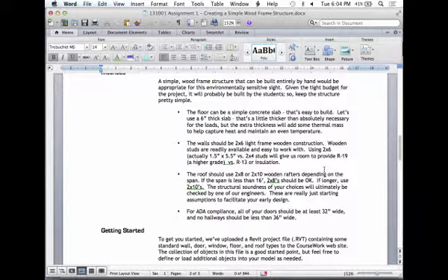I'm going to draw this in section. So the slab might look something like this, and it's going to be about 6 inches thick. If I really got precise about it, and we don't need to do it for this first model, but we're going to ultimately start putting some detailing in the slab. So the slab would probably have a little edge detail that looks like that, where we thicken up the edges under the places where the bearing walls will come down, just so that they don't crack right there. We want to have a little extra support. It's like a little footing built into it.